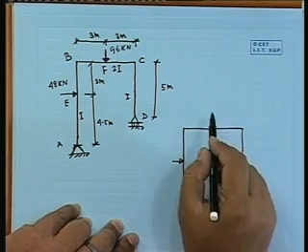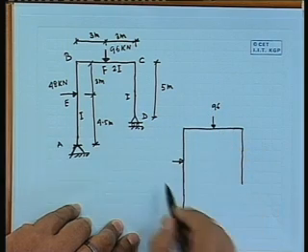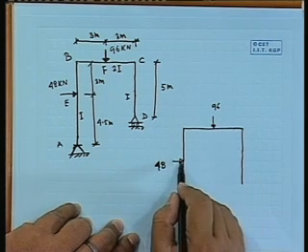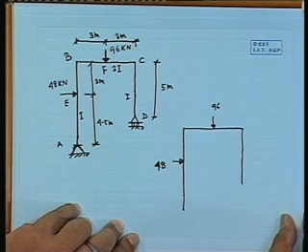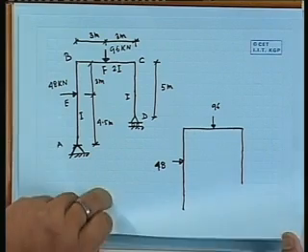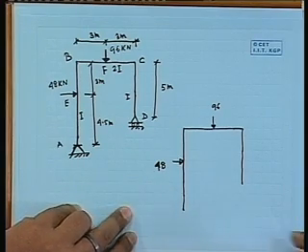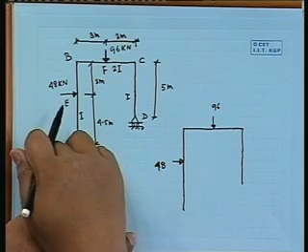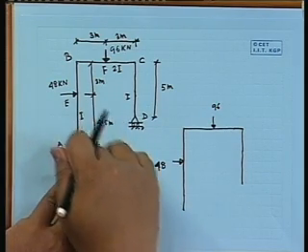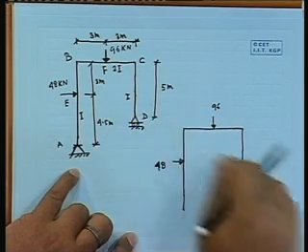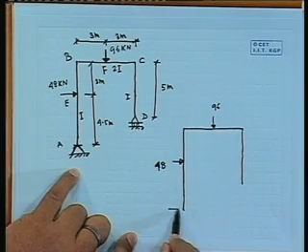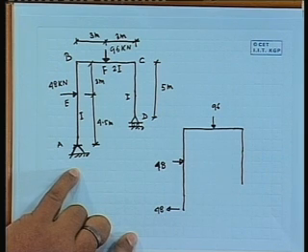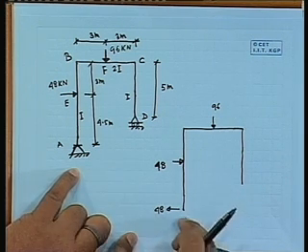Right. So, say I am putting only 96, not kilonewton, in order to make the diagram as much clear as possible. Now, this point is hinge. So, it can carry axial force, it can carry horizontal as well as vertical, and this will carry only vertical. So, all the horizontal force will be carried by this support, right.